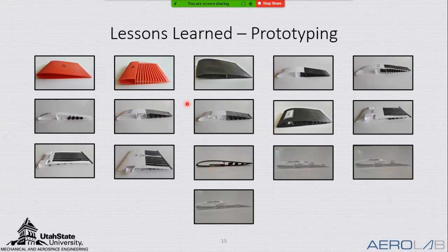Along the way, we also learned that there was a good ratio of PLA to TPU. And for these purposes, this is a 5-inch section of TPU, and interspersed are 5 1/8 inch span-wise thick ribs of PLA. And that was in order to prevent the surface from buckling. And we found that was a good ratio for that.